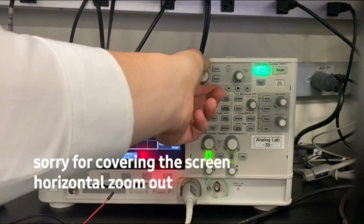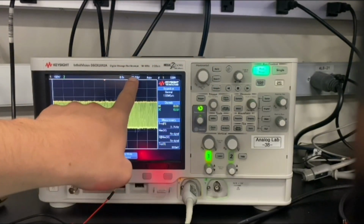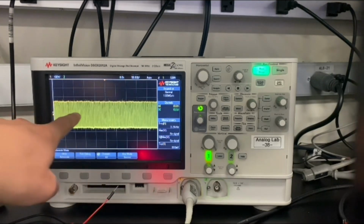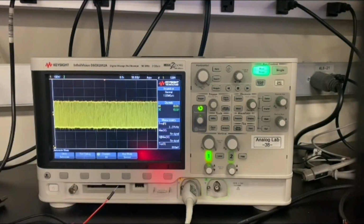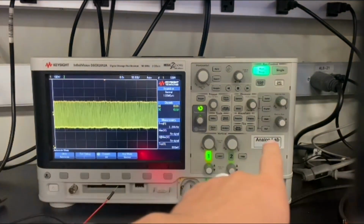We're going to want to zoom way out. Zoom out until you see at the top this dimension reading is 50 milliseconds. You should be able to see a big cloud of the signal at any given point in time. We're going to show you how to do the fast Fourier transform setting on the oscilloscope. That will tell you what frequencies are present in your signal.